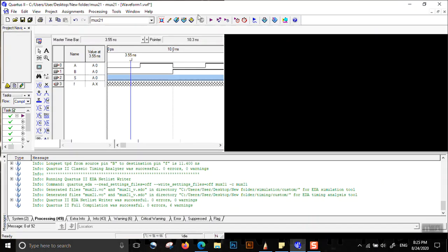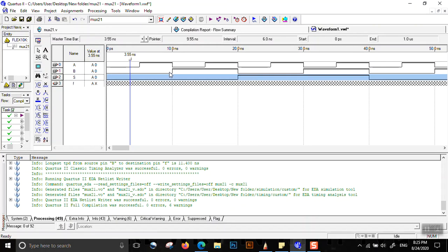Why are we considering this is 10 nanoseconds, then this is 20, then this is 40? We're doing that because if we see that we'll get all the logic, all the inputs sequences here. We have 0, 0, 0, 0, 0, 1, 0, 1, 0, 0, 1, 1, 1, 0, 0, 1, 0, 1, 1, 1, 0, 1, 1, 1. We have all the logics here. In order to get all the logics, all the clocks need to be twice the previous one. Okay, these clocks have been defined.